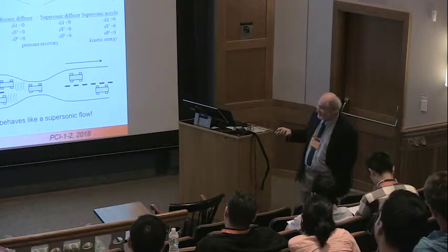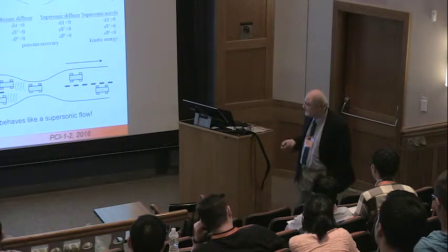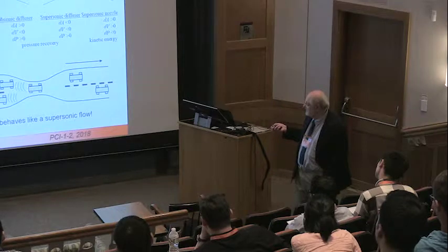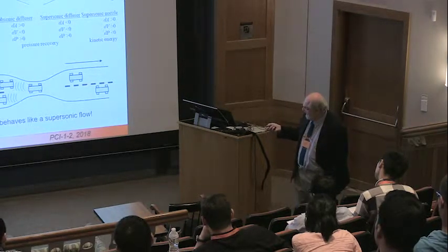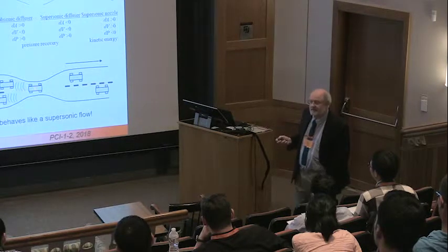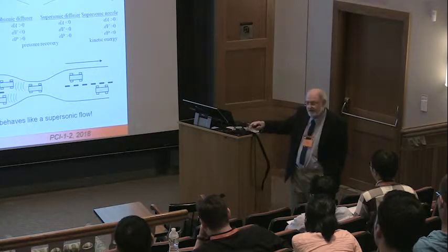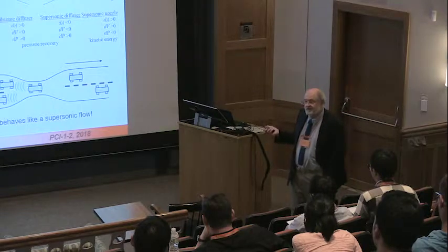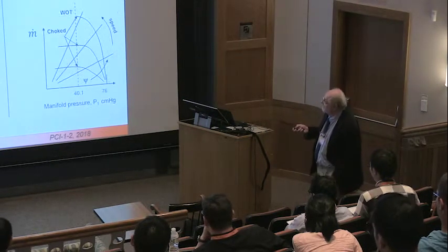A subsonic flow speeds up like you would expect it should do, right, through this intersection. And why is that? Well, the reason is that this guy here is sending information about his position to the guy immediately behind him. And this guy over here knows nothing about that guy back there. So he hasn't had this communication process occurring. Information along the left running characteristic, if you like, never reaches back here. It's like a supersonic flow. So that's just an interesting thing to remember.